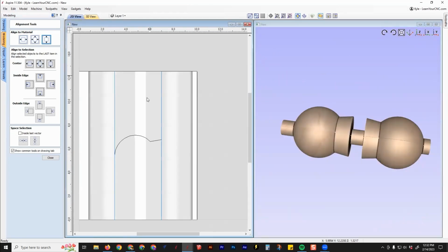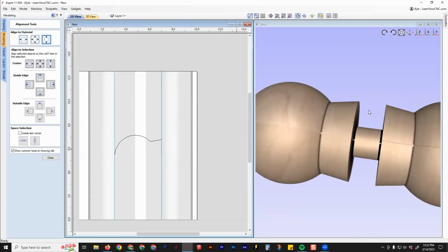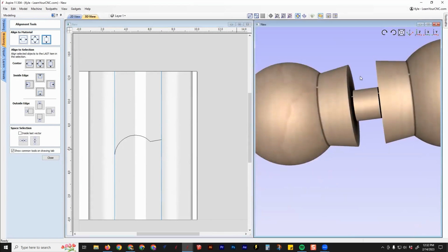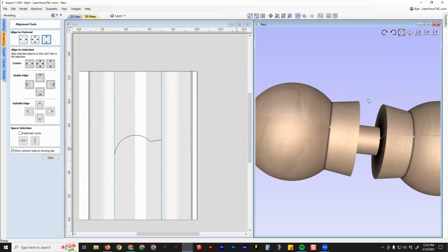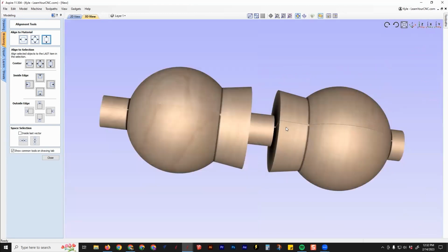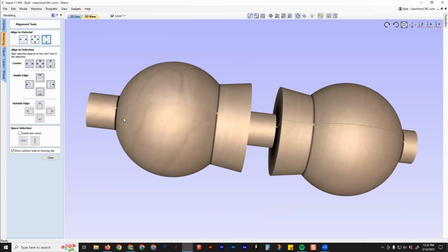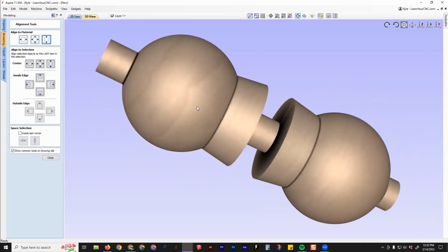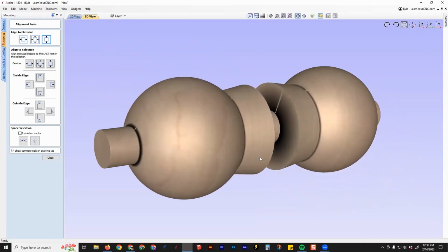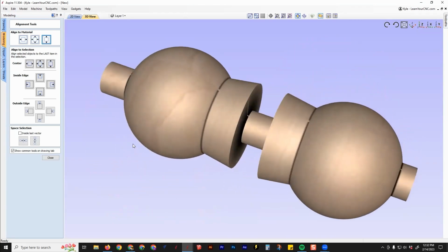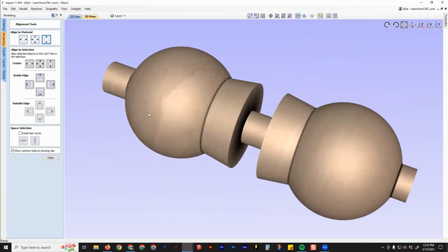Which tools do you recommend for that, Kyle? An end mill and then a ball nose to finish it? You can use an end mill for the roughing stage and then a ball nose to finish it up, or you can just use a ball nose to do the roughing and finishing. You won't need a very detailed ball nose for this. You can probably get away with a 1/4 inch ball nose.